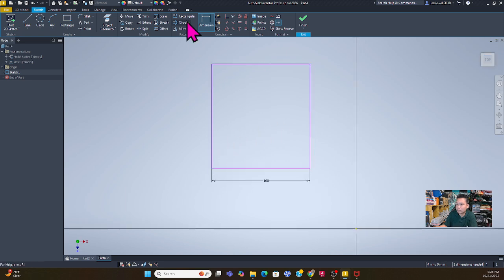All right, next I will construct a rectangle right here, and then I'll trim it out. At this point, before I do anything further, I'm going to click on this right here. Make sure that you hit the shift key to select both of them, and you're going to make them collinear, so make sure that they are straight. Because if you don't, I'm going to make that mistake now. I'm going to the dimensions, and you can see what happened when I put the dimension in here. This is 50, and you can see that they are jumping up right there, right?